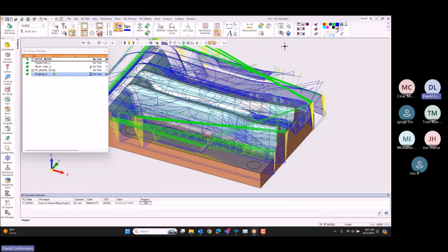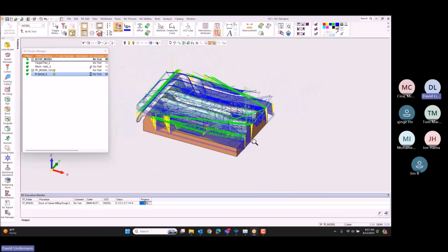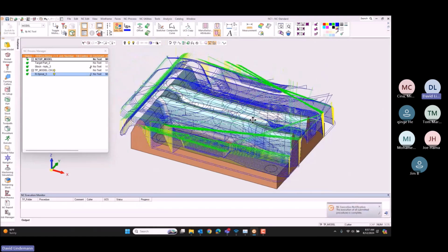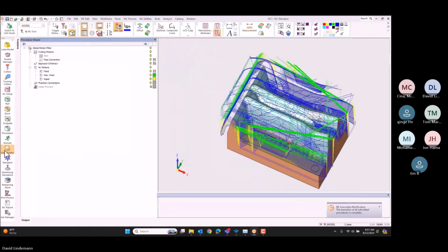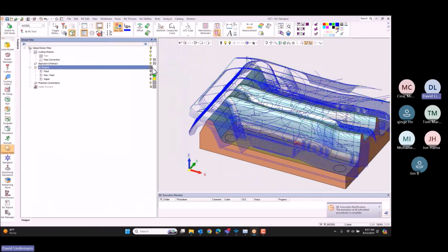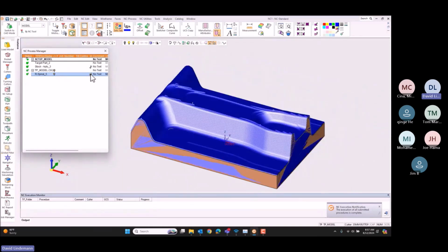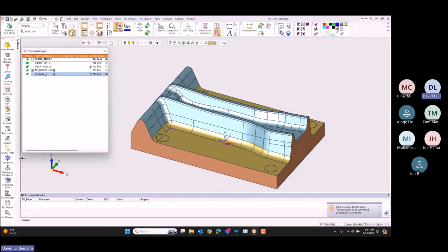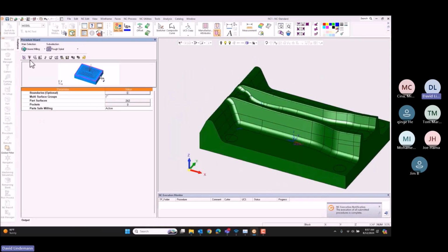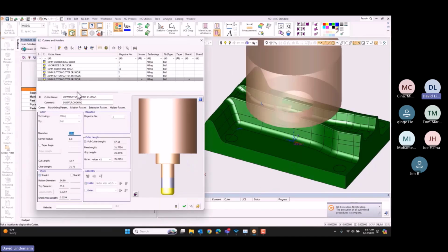All right, so here you can see the cutter motions now as it takes its first rough cut. And if we want to, we can isolate so we just see what the cutter path motions look like. Okay, so I'm going through, check now my stock. You can see the 2 mil everywhere, plus the stair stepping that goes on with that bull cutter.